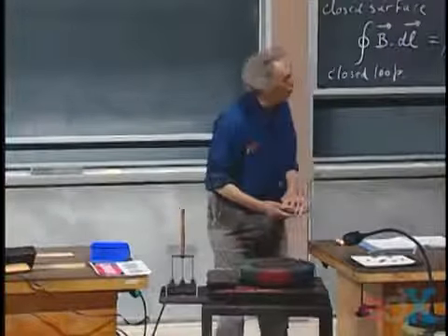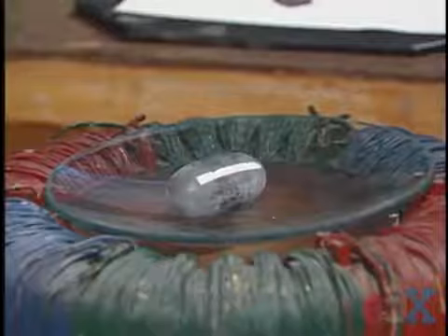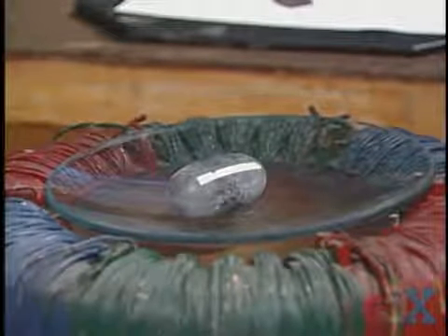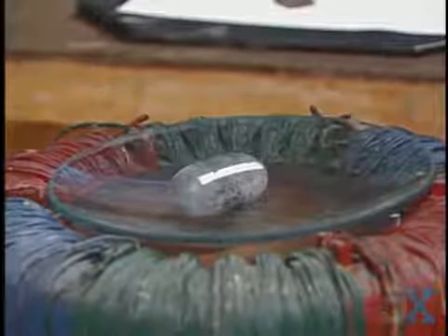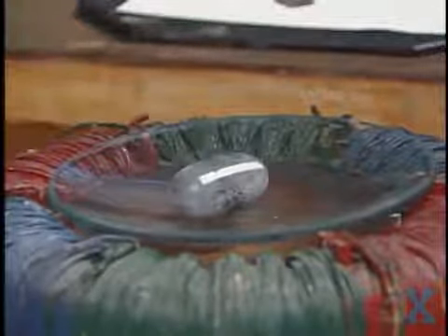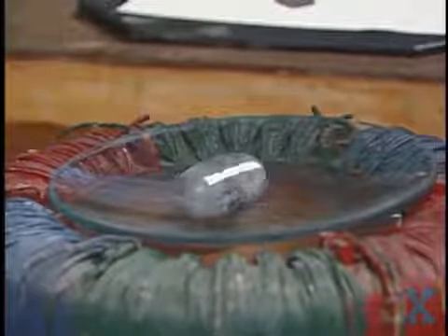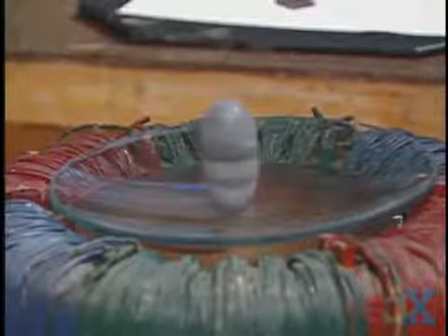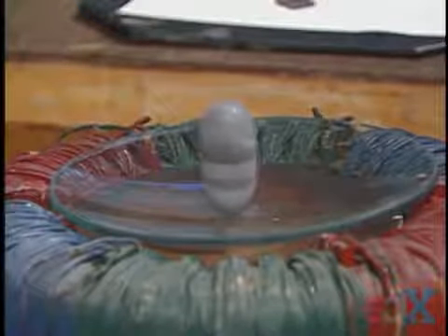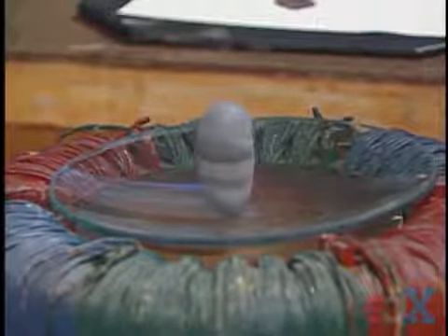Now here I have a conducting egg. And this now has ample possibilities for eddy currents to flow. And so now if I give these coils the right current, the three-phase current, it's spun up, the magnetic field acts on the eddy currents, and it starts to spin. And I have actually tried to measure the rotation rate.